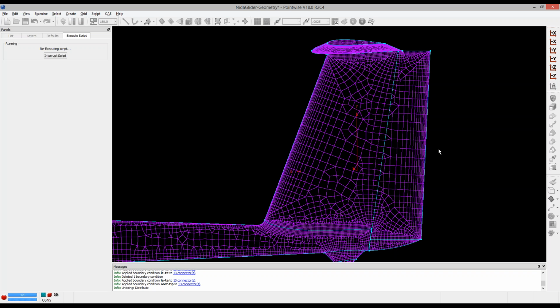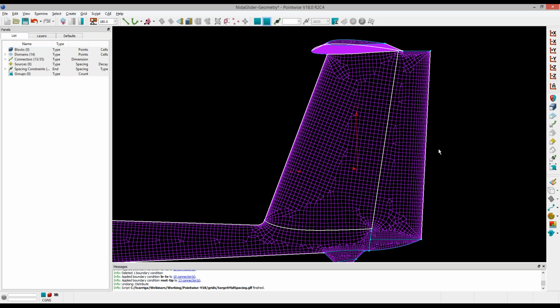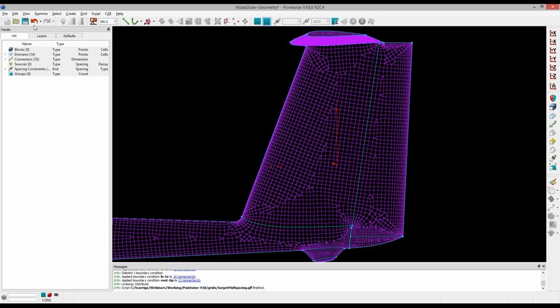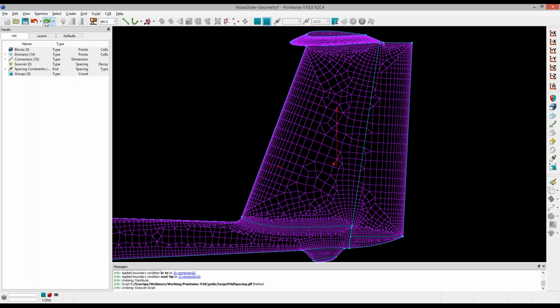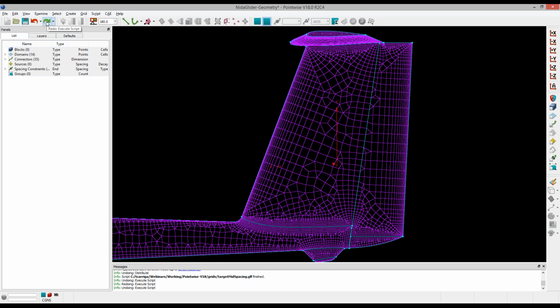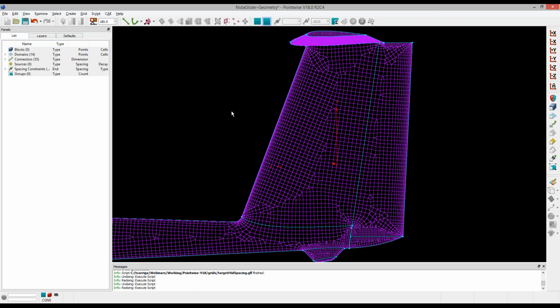All right, so it's going around all of those connectors I selected and changing their distribution function to growth, calculating how many layers they need, and here is the result. And you can tell I really love scripting, and the result that I'm seeing here is absolutely fantastic. Just for dramatic effect, let's undo that and redo that. You can see we went from here to here.